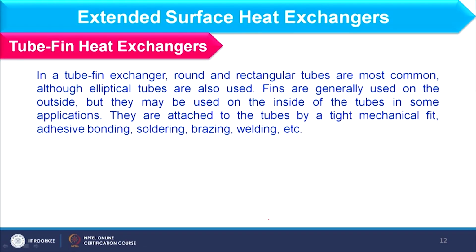So it is called the extended surface because we are extending the heat transfer area in a particular region. Because of that we are using plate fin heat exchangers, and tube fin heat exchangers we also use. Round and rectangular tubes are most common, and sometimes we also use elliptical tubes, and fins are generally used on the outside.